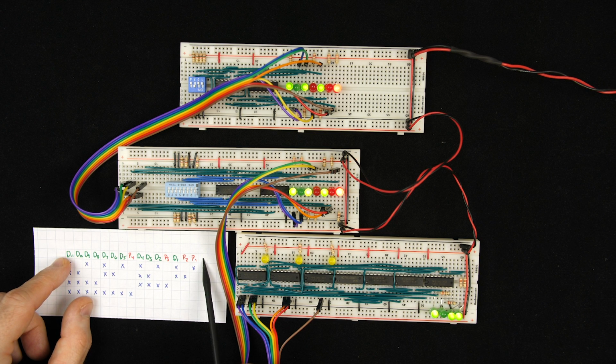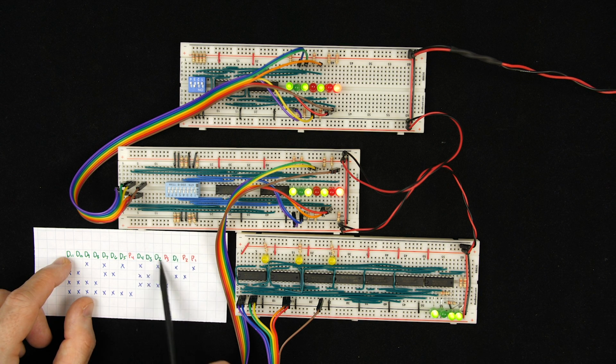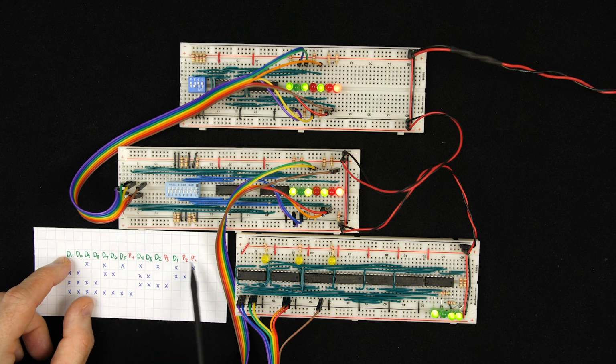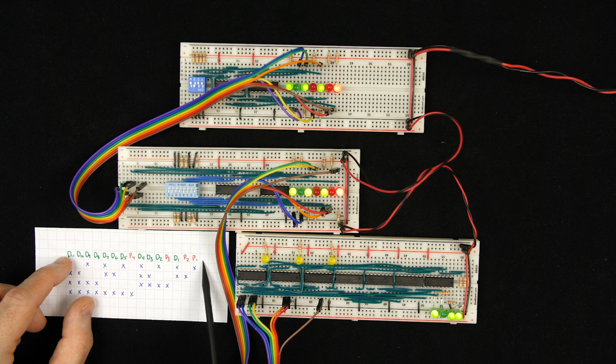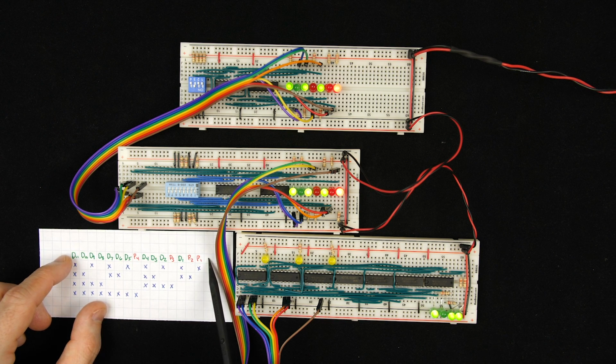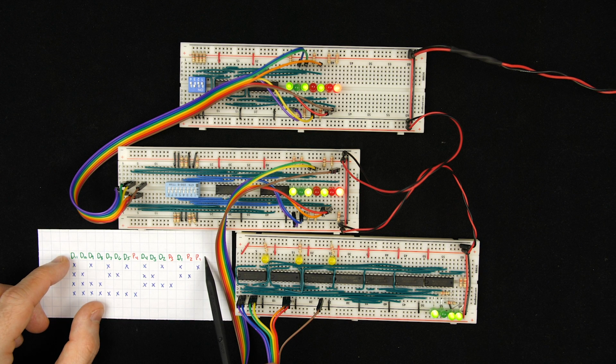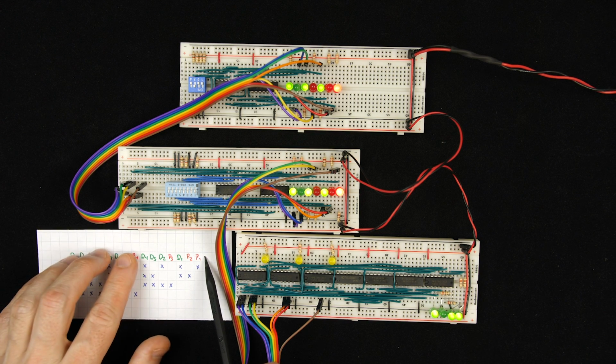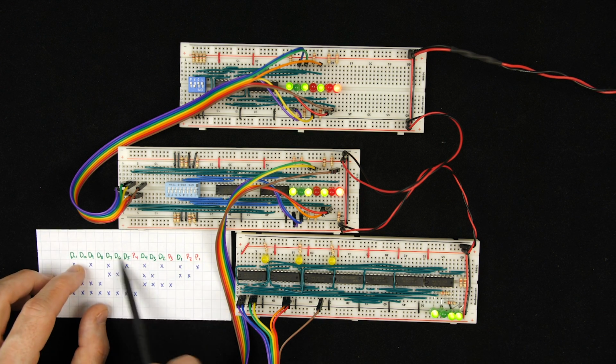It doesn't help you with error correction at all, but it gives you a second check, so that if you have an error that you're able to correct, and you have another bit that's wrong, then that extra parity bit will tell you if you have a 2-bit error. That's a very common use of that extra bit. Now, I won't build all the circuitry to add that, but you can use your imagination there. That means that in practice, this Hamming code scheme will usually let you correct 1-bit errors and detect any 2-bit errors.